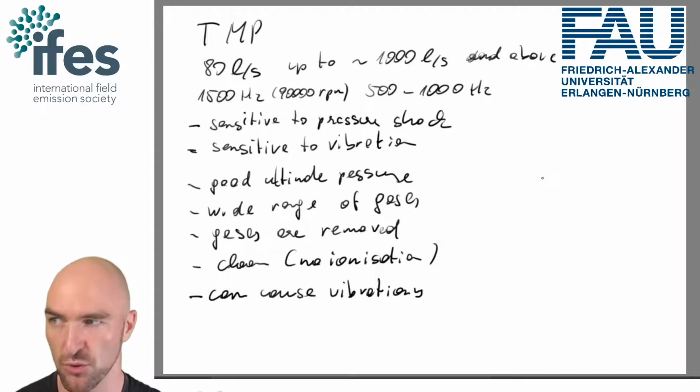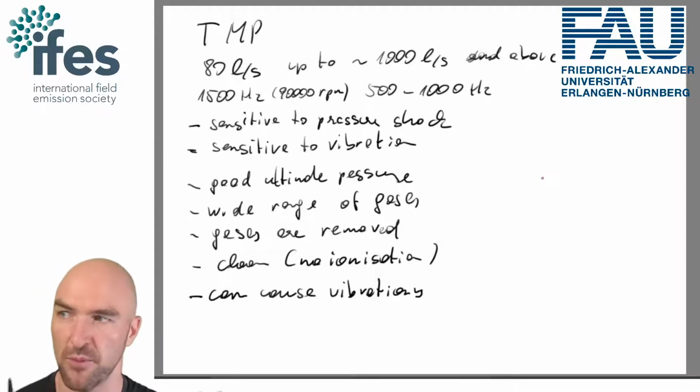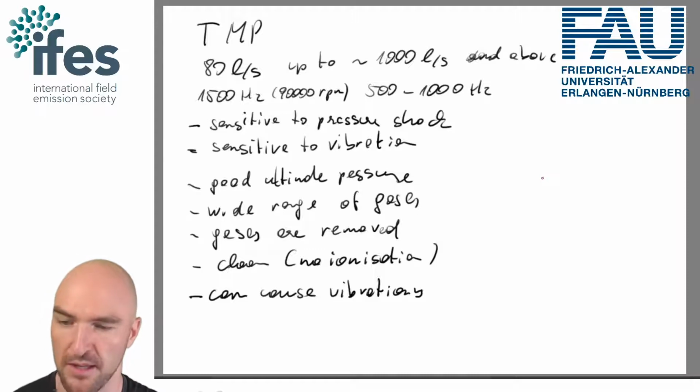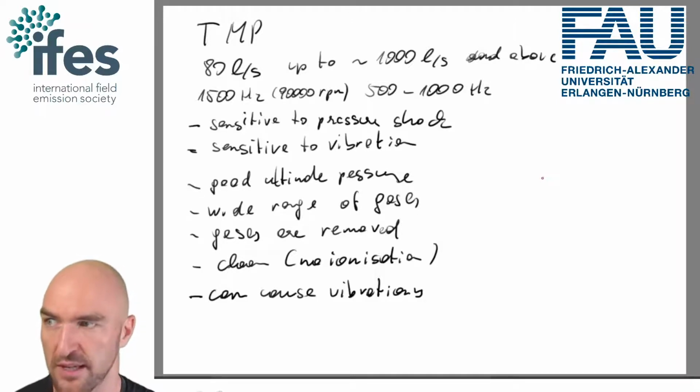It's not going to be as super clean as some of the other approaches that you can take with sorption pumps, but you can combine them with sorption pumps. For example, you can use a non-evaporative getter pump together with a turbomolecular pump, which can be very effective. And so you can do some pump combinations there as well.